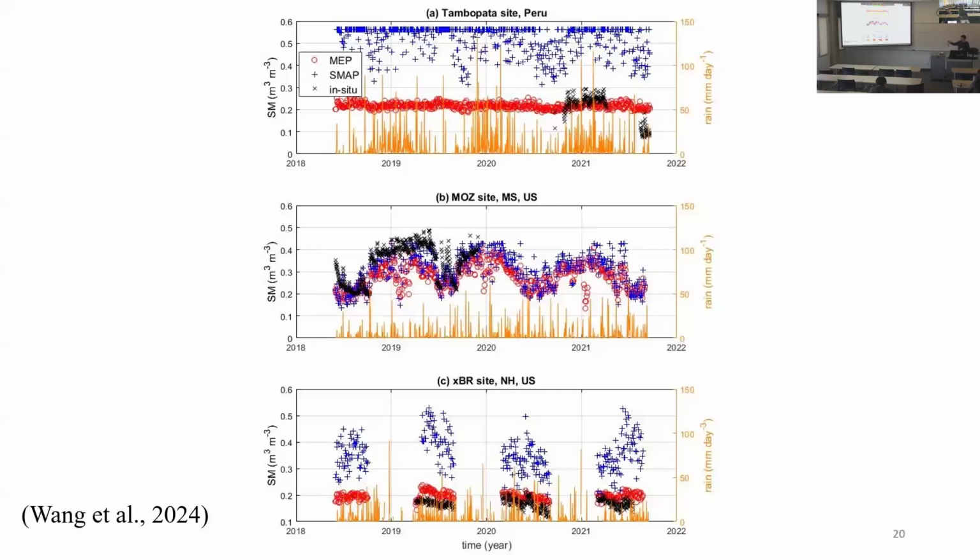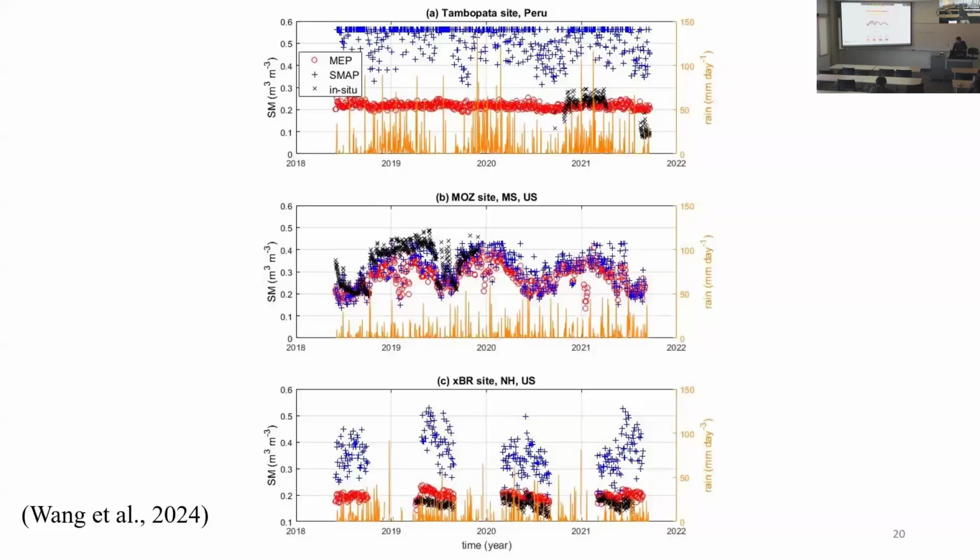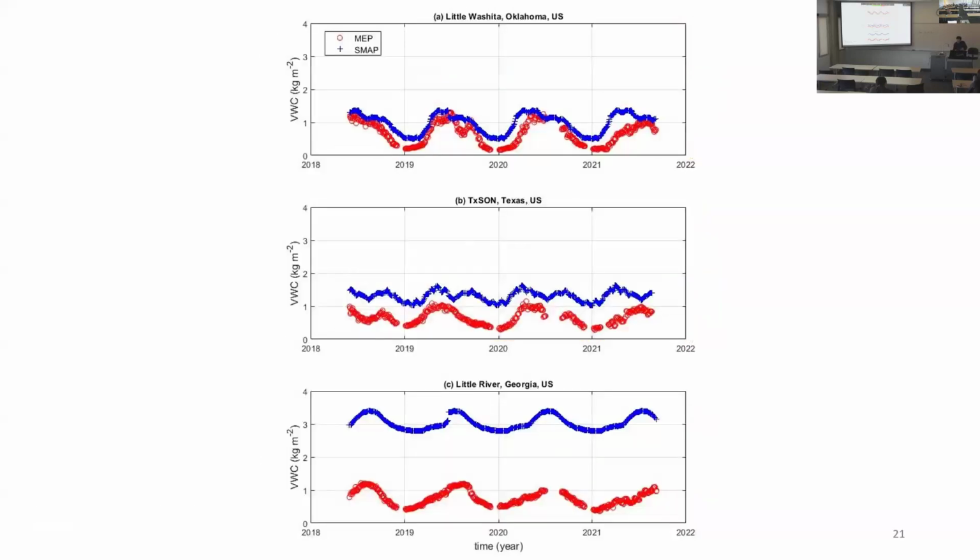So at the same time we can retrieve the soil moisture. This is a simultaneous retrieval of the vegetation water content. In the current SMAP algorithm, that has to come from somewhere else, not from their retrieval. They call it ancillary data, supplementary data from elsewhere. But we can retrieve soil water and vegetation water at the same time. So we get a simultaneous retrieval.